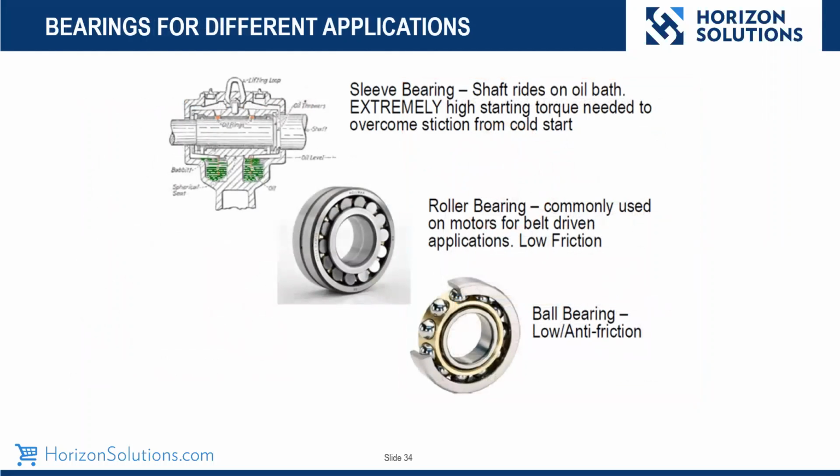Different types of systems. Some may still see that they might have on the very top, that's a sleeve bearing or a babbitt, whichever way you call it. I've poured a few of those myself, chuckle. But it has high stiction. I'm sure everybody that uses it is aware. It was predominantly used at the turn of the century. And then of course with the advent of the ball bearing and the roller bearing, this sort of eliminated the need for babbitts.